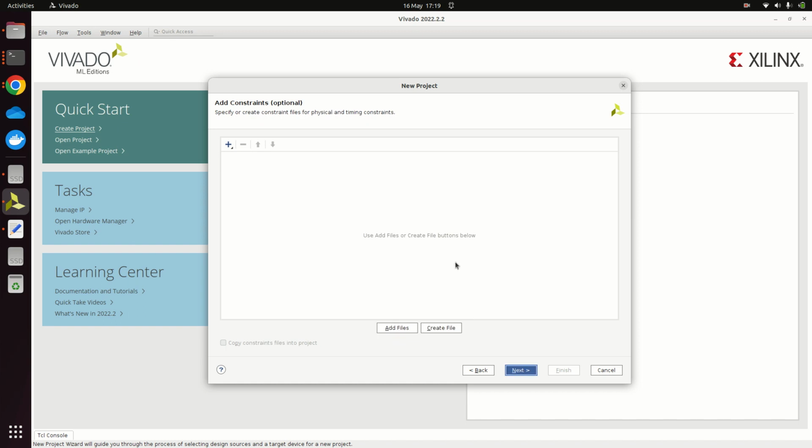The next file required is going to be the add constraints file. The constraints file is important because it's going to link your hardware pins to the pins that you are going to connect your created model with. You will be defining which pin of the FPGA in hardware you are directing the schematic to. That's the ZCU102 I am having. You can have the others as well, but those are the pins that I'm going to connect from here to there.